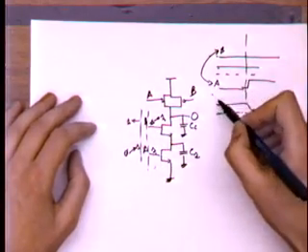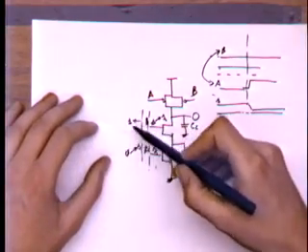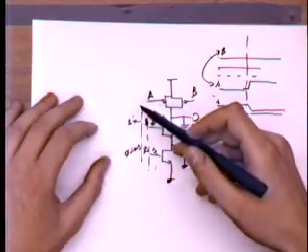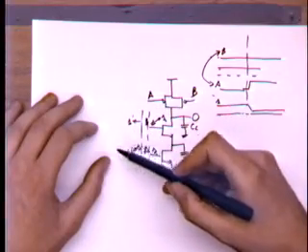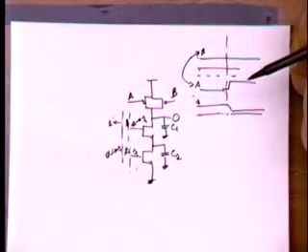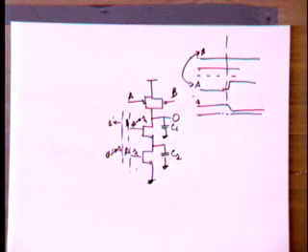The output always goes from 1 to 0 in this case, because in the end you always have both inputs at 1, and it's just a matter of whether you turn on first the bottom device and then the top device, or you turn on first the top device and then the bottom device. So in this case, it's possible that what you said is correct, that the second transition is faster, but the motivation is not correct.